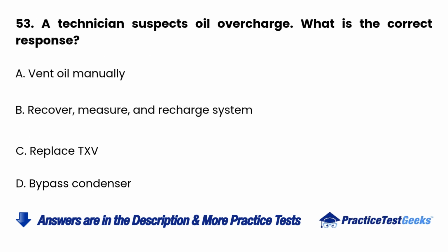53. A technician suspects oil overcharge. What is the correct response? A. Vent oil manually. B. Recover, measure, and recharge system. C. Replace TXV. D. Bypass condenser.